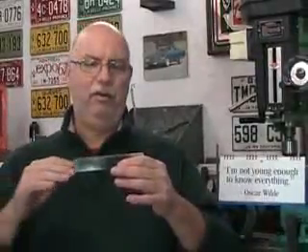Anyways, parallel within 1/1000ths of an inch without too much difficulty. And that would be the end of it, because my dimension here, let's say my height had a very loose tolerance, I wouldn't have to go out of my way to grind, measure, and work my way close to something very accurate.